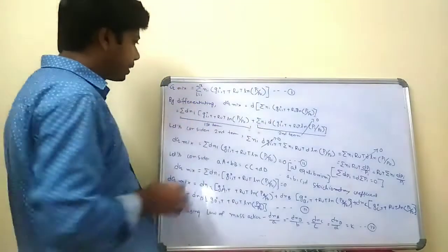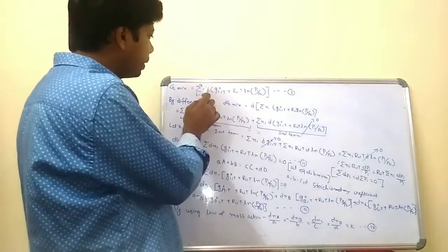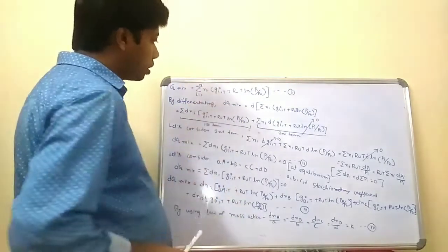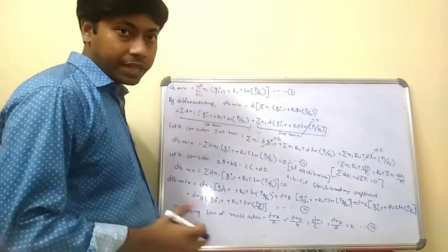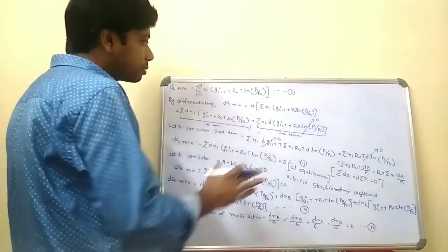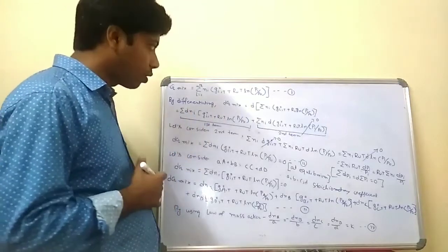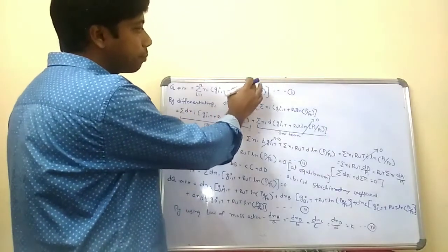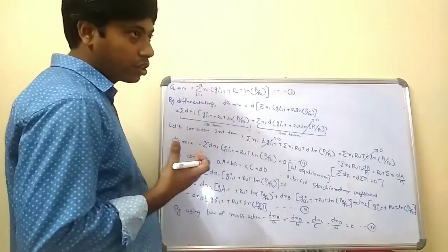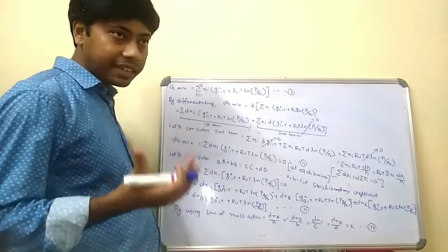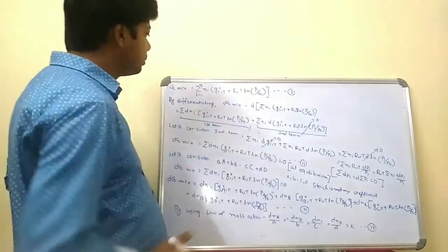So we already have that G mixture is equal to the summation of Ni into Gi0,T, which indicates the standard Gibbs free energy of the ith species at standard temperature and standard pressure, plus RuT ln Pi by P naught, where P naught is a constant, the standard pressure. So this is the G mixture.